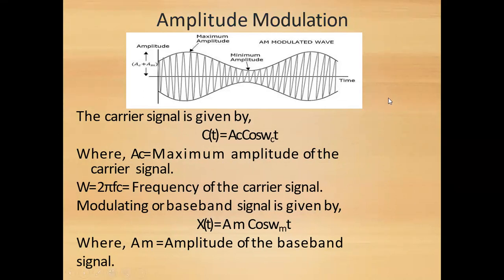So here one of the characteristics is varying. What is that characteristic? Amplitude. How is it varying? It is varying with respect to the input message signal. So the definition is verified, where the amplitude of this carrier signal is varied in accordance with the message signal.